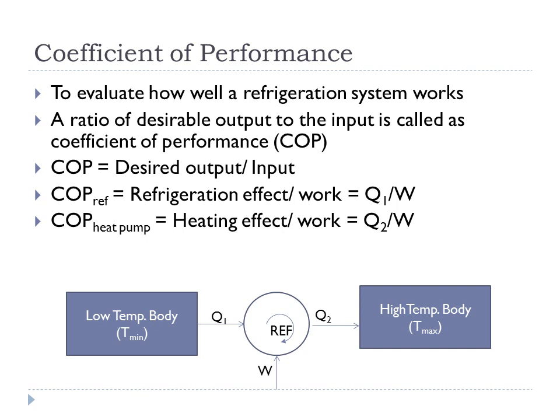So the COP of a heat pump would be defined as heating effect divided by work input. So it is equal to Q2 divided by W. And with some manipulation, we can see that COP of a heat pump is always greater than 1 because it is equal to 1 plus COP of refrigerator.